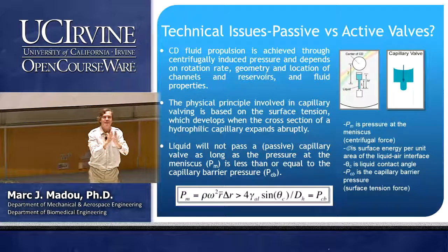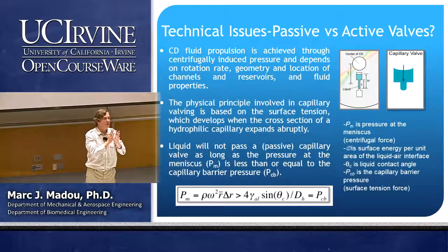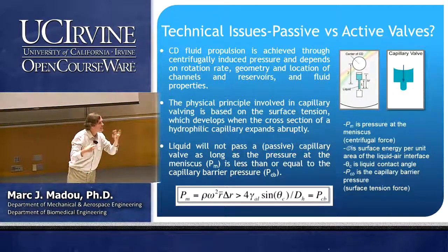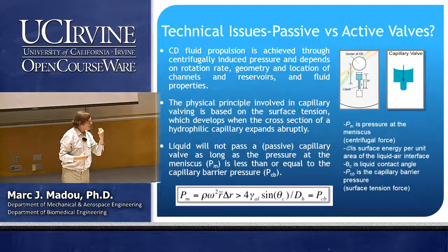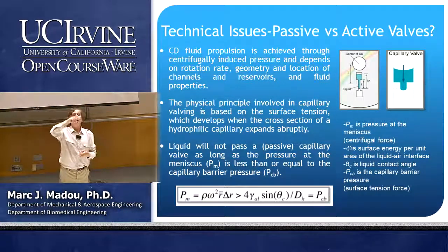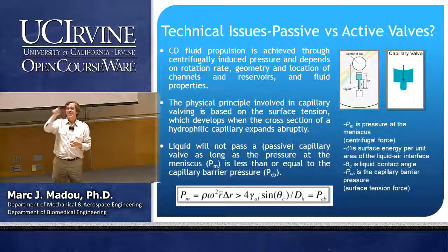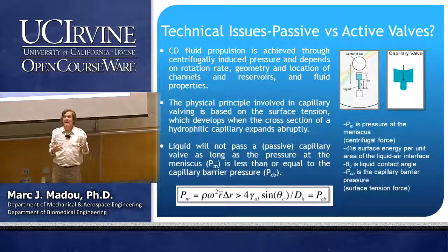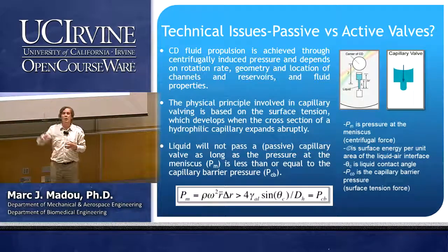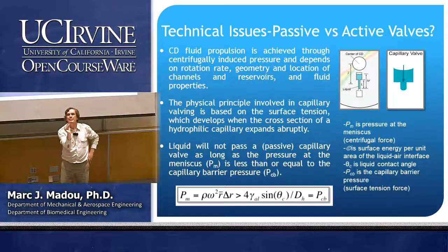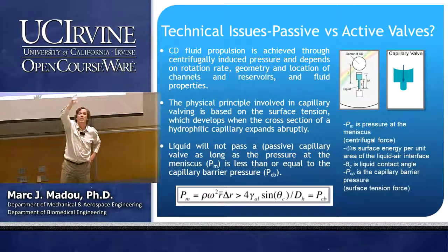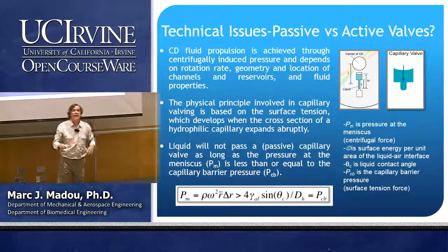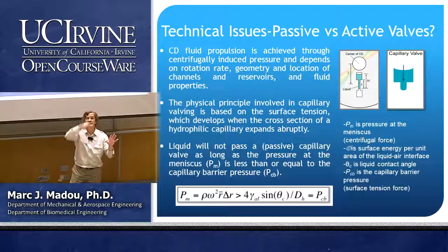Because there the liquid is spinned less. If I go to the 100 microns, the liquid is spinned much stronger. I have to go to higher RPM. That means I have a valve that depends only on how fast I spin. And that's kind of neat, right? I can put 8, 9 functions on that CD and design it such that because of the capillary size or depending on where they are on the CD, this one goes first and this one, this one, this one. We have done systems where we had 7 steps.